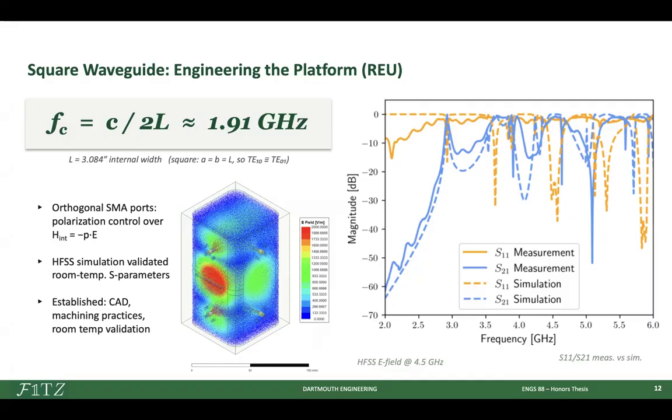Yeah, it could be due to how it was machined. This was me still learning, and there's a lot of trial and error with this square waveguide. It could also be just how these measurements were taken, or the orthogonal quartz weren't properly orthogonal in place. Wait, but is the agreement worse than the normal waveguide? This one is worse, yeah, 100%.